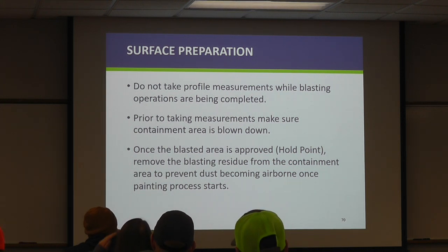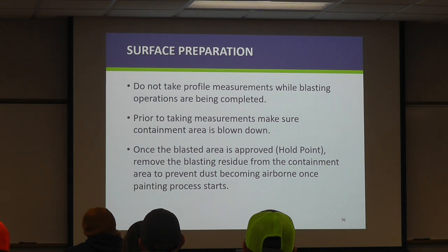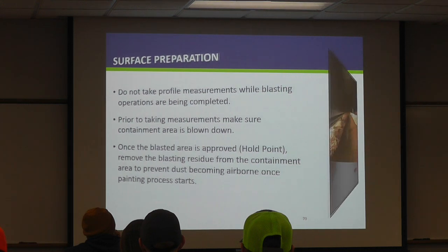Once blasting operations are completed, you get a chance for everything to clear out. You can go in and take these profile measurements for anchor profile, and depending upon the method used, the blasting residue is likely going to have to be blown down before you will actually get decent measurements. So when the contractor's done blasting, they may need another 20 minutes, half an hour, whatever, just to go rip through that section real quick and blow everything off the girders. Might be tough checking the bottom flanges and things like that otherwise.